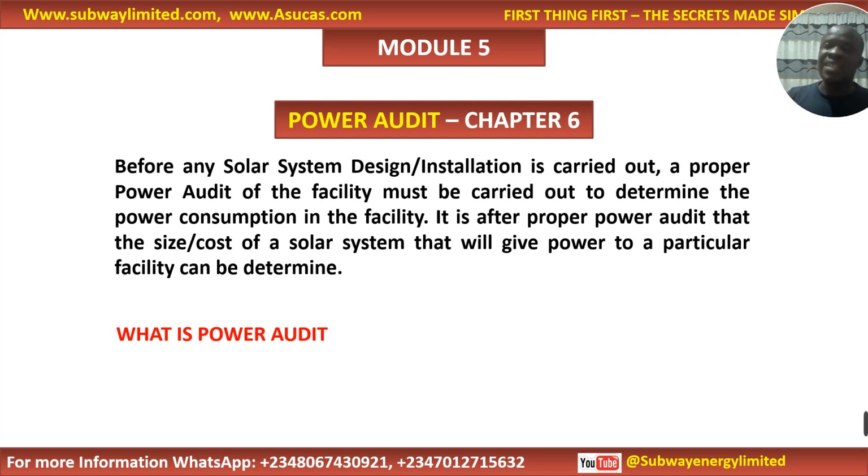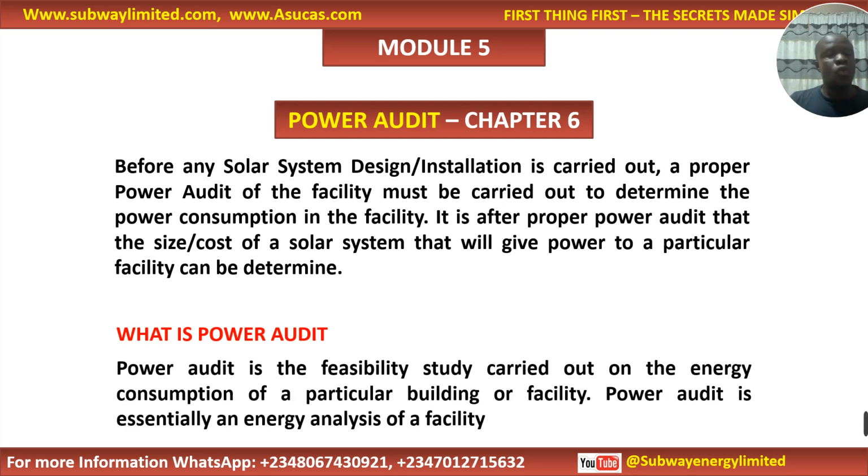Power audit is taking inventory of the electrical load, the roof dimension, the site, the facility properties to enable you size a system that will run the electrical load in that facility. So basically, power audit is the feasibility study carried out on the energy consumption of a particular building or facility.